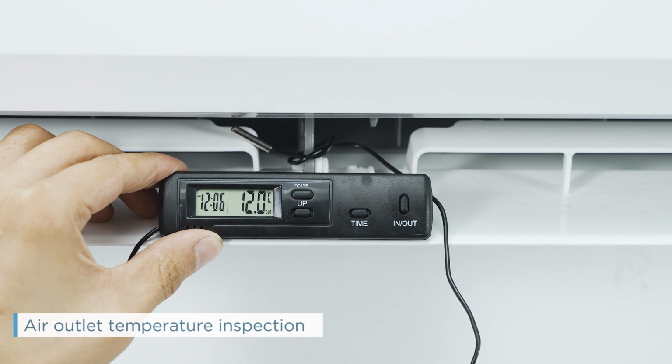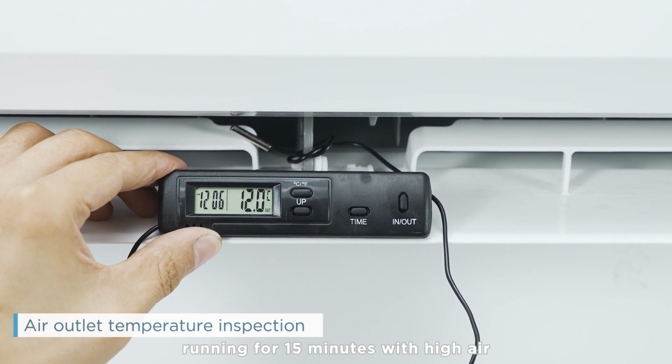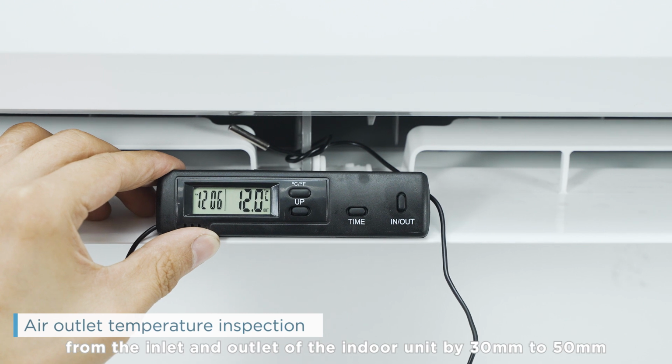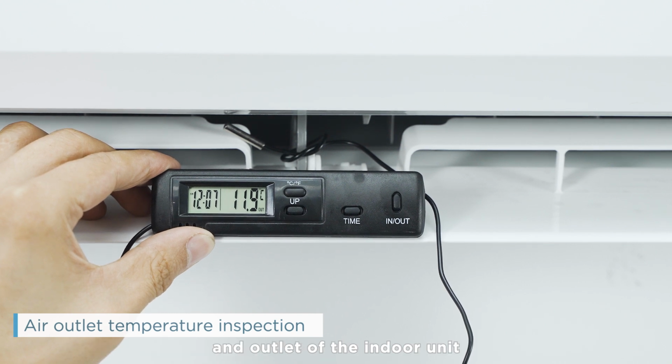Air outlet temperature inspection. After setting the refrigeration mode and continuously running for 15 minutes with high air, use a thermometer to keep the temperature sensing probe 30 mm to 50 mm from the inlet and outlet of the indoor unit and detect the temperature difference between the inlet and outlet of the indoor unit.